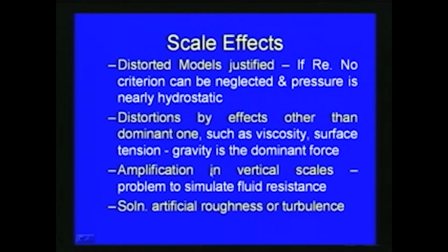The third case is amplification of vertical scales, the problem of simulating fluid resistance. In these kinds of river or estuary models, the vertical scales are not met, so the fluid resistance has to be artificially simulated. The roughness of the bottom or the boundaries may not be met, so we may have to add artificial roughness or generate turbulence. Amplification of vertical scales is a major issue.